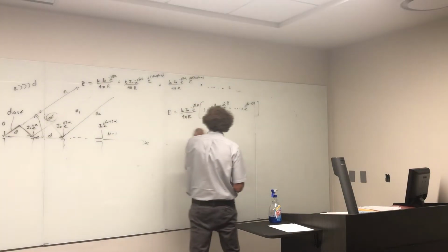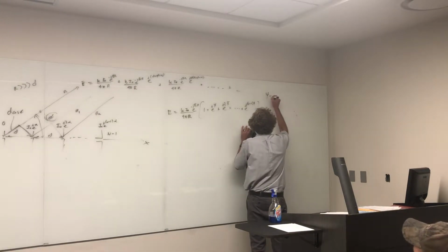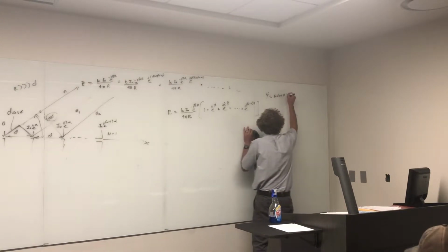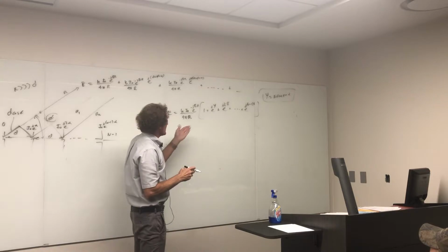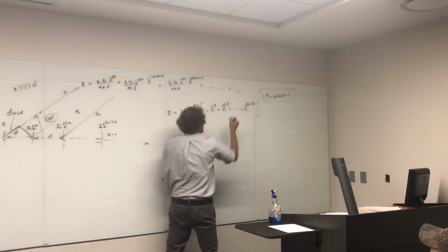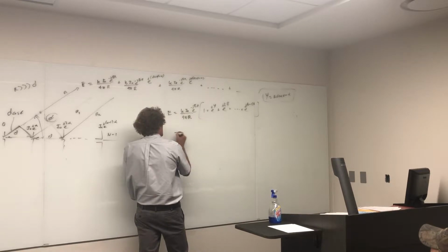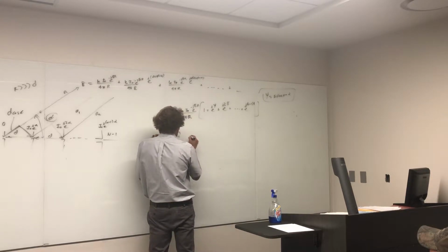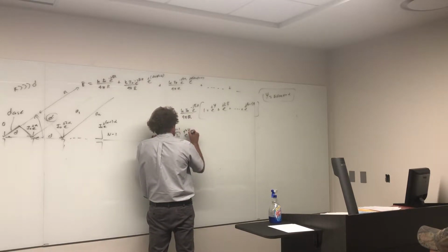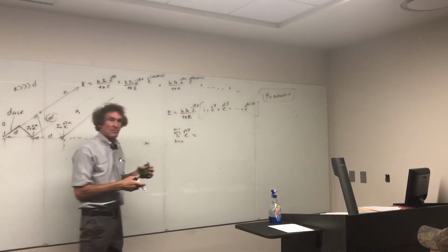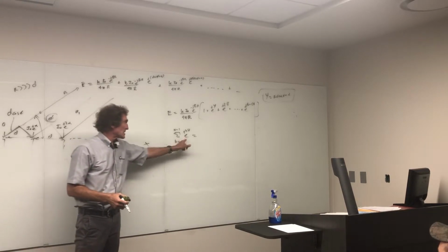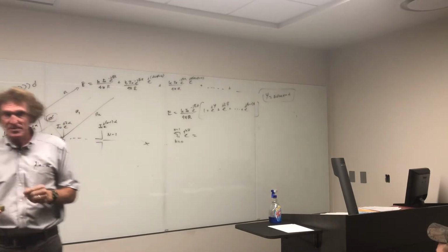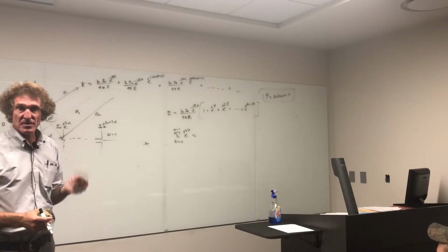So now I have this equation, and again, I'll put down psi is beta d cosine of phi plus alpha. All right? Don't worry, I'm going to break it off in a second. When I get this, what do you think this goes down to? Doesn't this look like a series? And really, I could have a series from n equals 0 to n minus 1 of the term e to the j n psi. Isn't that right with all that exponential stuff, 1 plus e to the j psi plus e to the j. Now that's a very classic one. That's the geometric series, a to the n, where n sum from 0 to n minus 1.